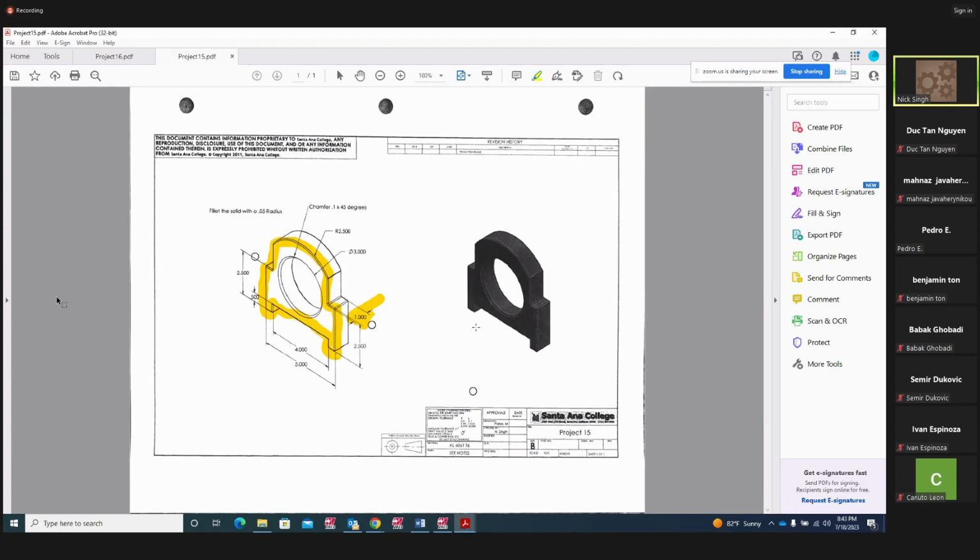So in the front plane, let's create this body right here on your front plane. Create this body. I'm going to start my origin right on the center where we can create this big circle. That circle is 3 inches diameter. And then we can create, let's start with the rectangle right here, a 2.5 by 5 inch rectangle. Let's do that.